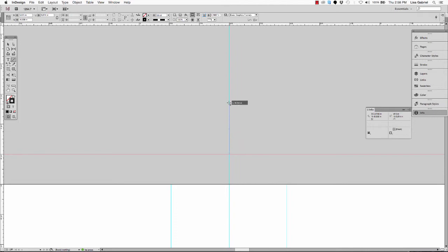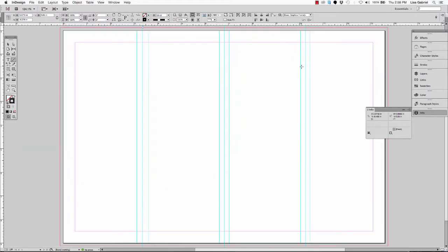And as you can see, the smart guide is telling you how far up. You can also type it in here, 0.25, and over here in this region for L, it gives you the line height. Okay, you can type it in, and you can see that I have just drawn a dotted line starting at the bleed edge and dragging up. Okay, so now Command 0 to put yourself back into fit to window.